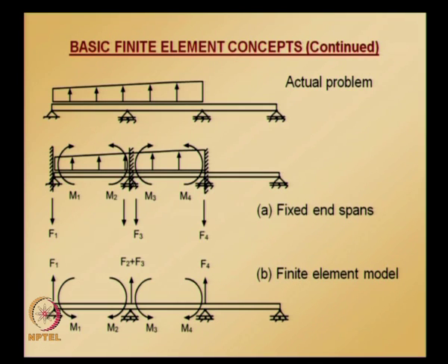I showed you displacement, bending moment and shear equation solutions. Similar solutions you can obtain from any standard or elementary mechanics of material books, and using those values you can find the fixed end moments and shear in each of the spans.